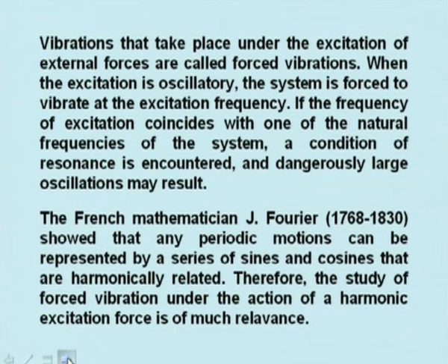So we are mostly interested in the steady state response. Then the system will vibrate with the excitation frequency. If the frequency of excitation coincides with one of the natural frequencies of the system, then we get a condition of resonance in which dangerously large oscillations may result. A large amount of oscillation takes place when there is a condition of resonance. So now we are going to study the mathematical treatment of forced vibration.